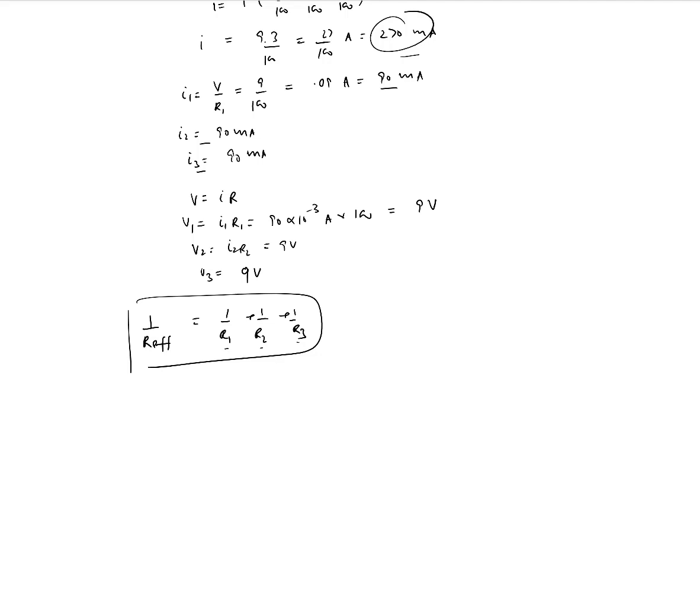So imagine what would happen if, let's say, you had an infinite number of these resistors in parallel, right? So let's say I have one, and I have another one, I have another one, and I continue this. Okay, I have infinite numbers. So this is R, this is R, this is R, and this is R, and I'm looking for the effective resistance of infinite number of these resistors, what would that be? So you can see that 1 over R effective should be equal to 1 over R, plus 1 over R, continue.